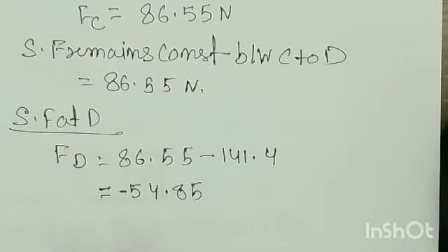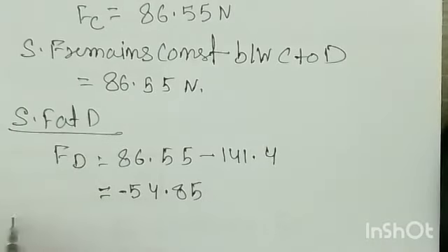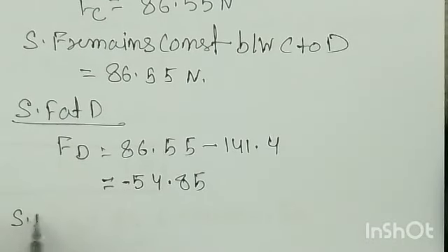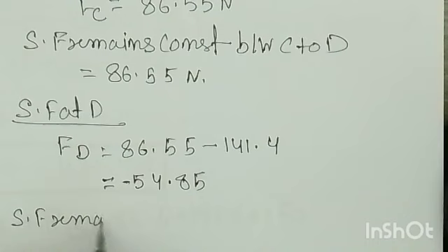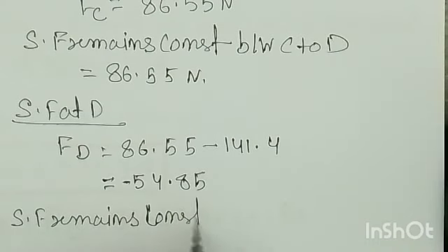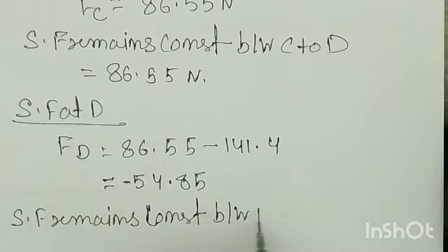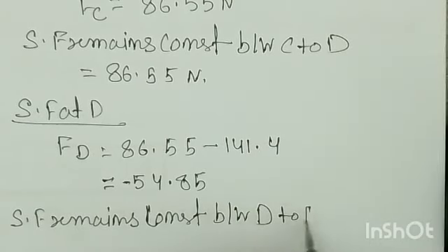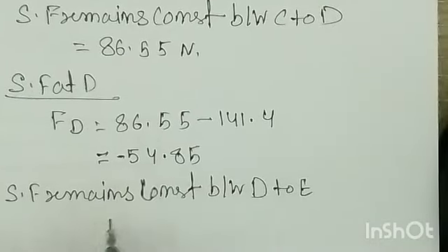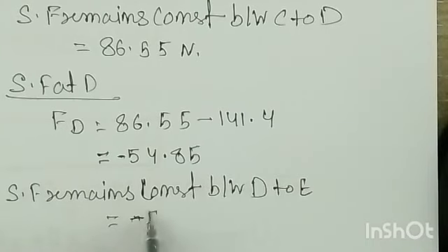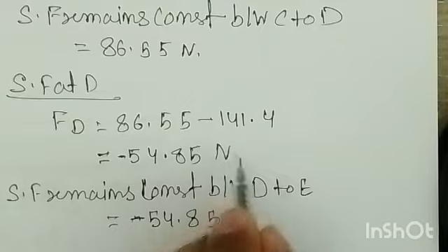Now again between D to E there are no other forces, so the shear force remains constant between D to E, right? And what is the value? That magnitude is still minus 54.85 Newton.